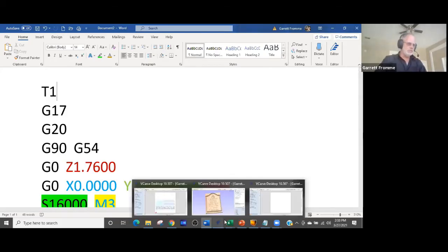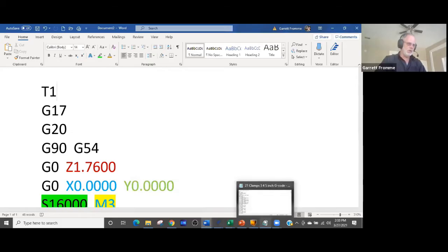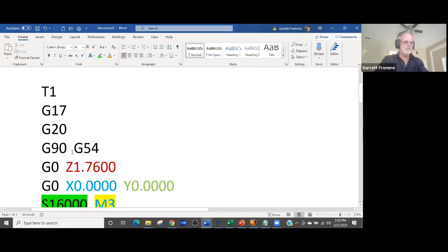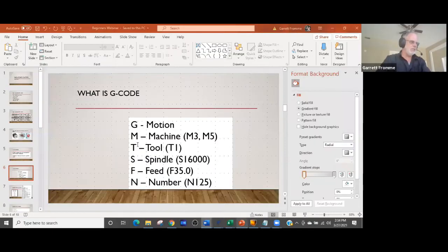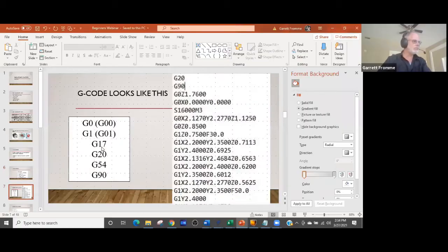I have an example up here somewhere. Like right here, you have G90 and G54. These can work together. But what we can't have is something like a G0 and a G1 at the same time, because they're part of a group, and they do that group differently. G0 says move as fast as you can. G1 says move at a certain rate. So those two conflict.